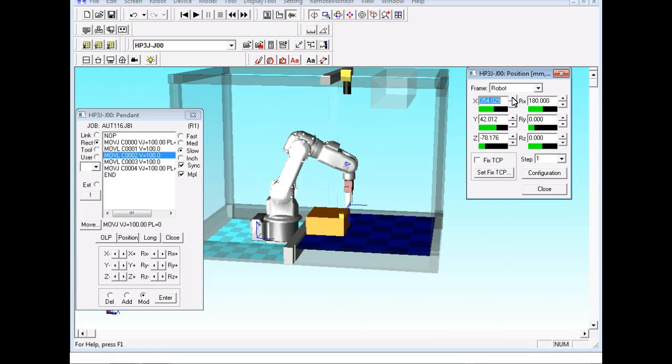Over there, if you were to collide that big old welder on the big Fanuc robot, well, the tips are copper, so they're a soft metal. You hit that thing against something, you knock it off just a hair, then your robot is going to be off a hair all the time, right? Does that make sense? So we can set up collision detection and all kinds of neat stuff with the simulation. Over there, the only collision detection we got is when you collide with something. Well, what I want to do in this class is let you see what a point-to-point robot programming method is. Everybody okay?